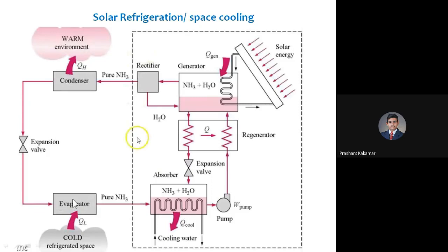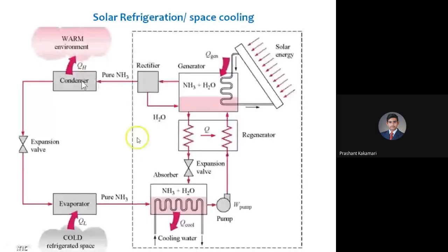So you can just remember in the solar refrigeration part, we can have the absorption chamber connected with the solar collector, and from the absorber unit, the ammonia vapors are collected back by separating the absorbed liquid, and only the refrigerant is separated and again taken back to the condenser. And from the condenser to the evaporator, we need an expansion valve to reduce the pressure and temperature.